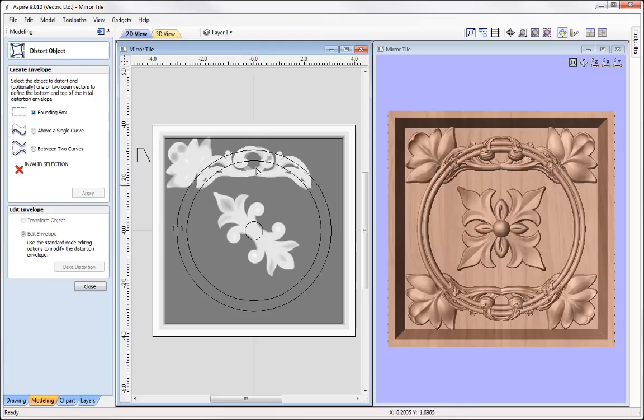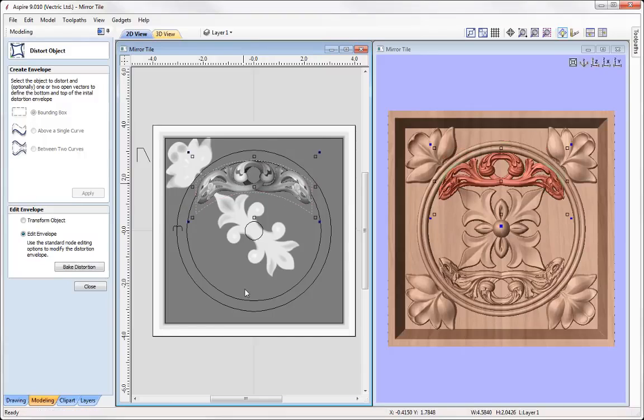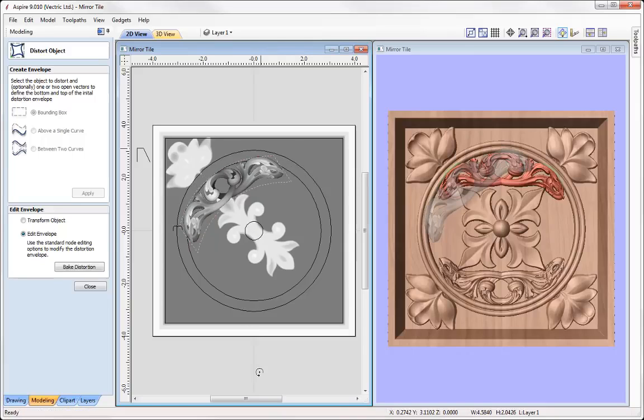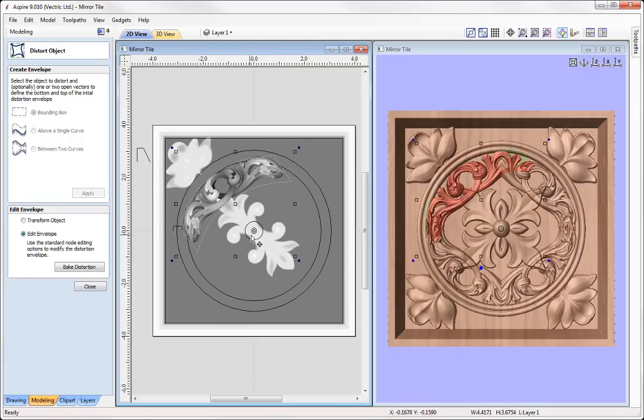left click just to stop that distortion there, then right click so I can just select it and then move it around. Okay, so you can see that there. Then what I could do is click on the center of the object to bring this target out. Now that target is the rotation center. I'm just going to put that in the center of our job so that then when I move that around we can rotate it about this center point here.